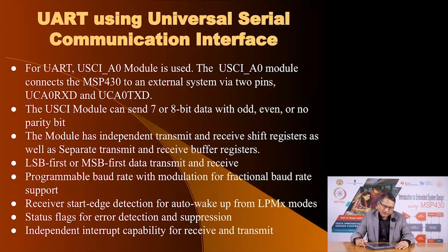Now, for UART, you have to use the A module, A0 module, and it uses 2 pins. Those 2 pins will be listed on the microcontroller as RxD and TxD. Of course, these pins are mapped on available port pins. The module can send 7 or 8 bits of data with odd, even or no parity. It has independent transmit and receive shift registers, which is how it is able to communicate in a full duplex